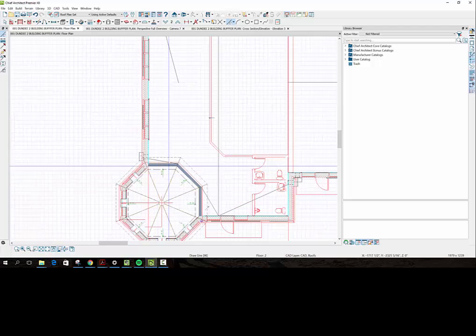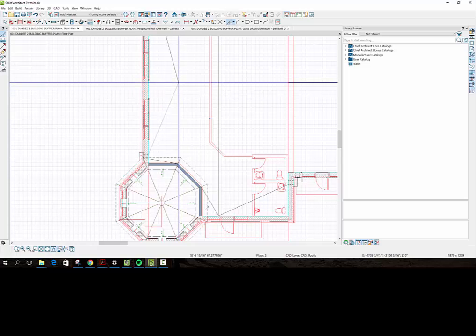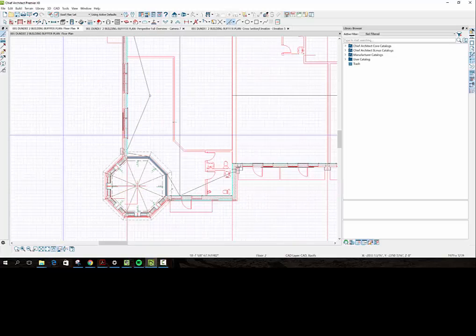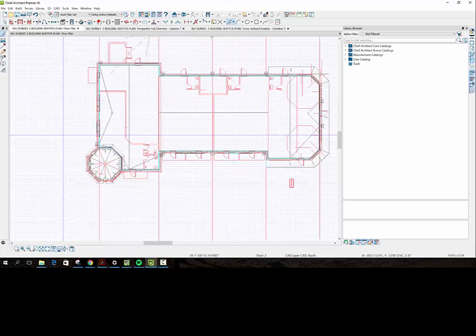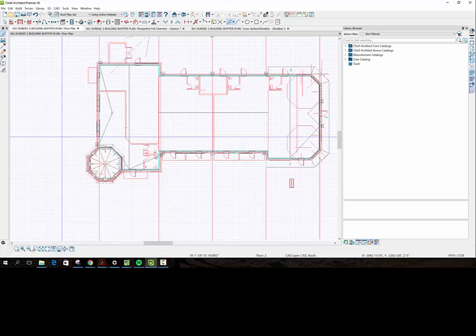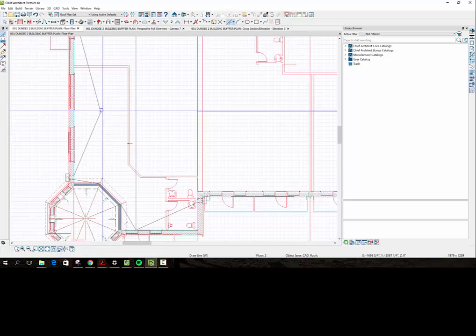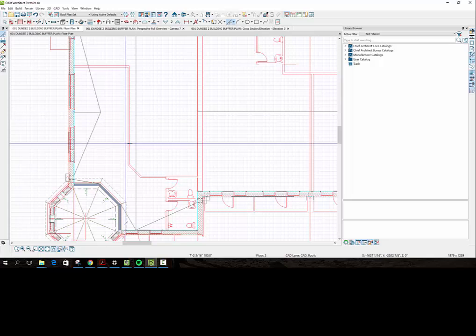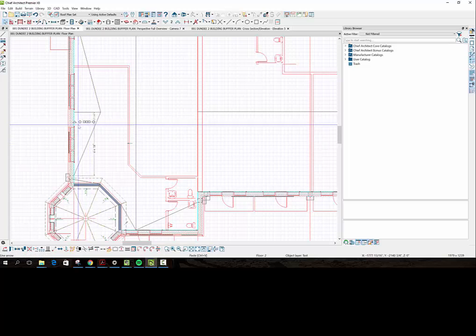And now we want to take it from here and use our control to stop it from snapping to some inch points. There, we're going to want a high point in our cricket. So we'll draw it from there to there. There's our high point for our cricket. Borrow this arrow, Control C, Control V. Rotate it around.